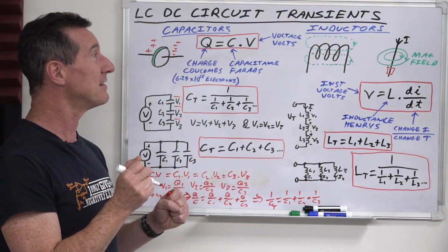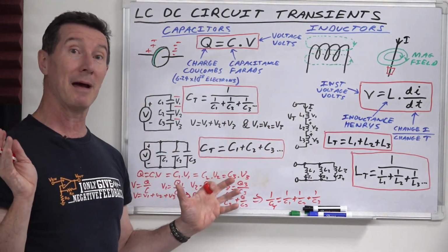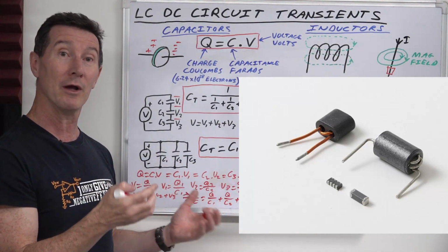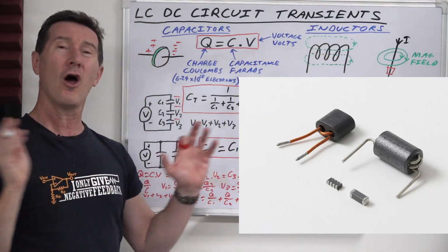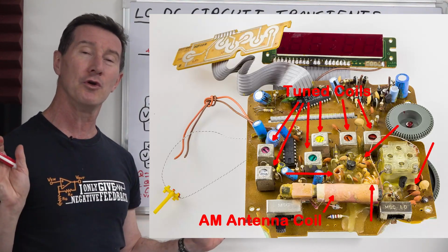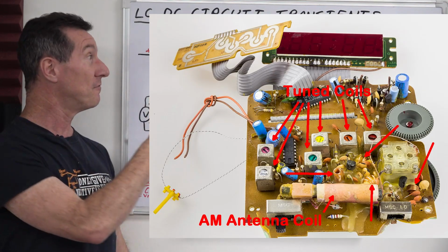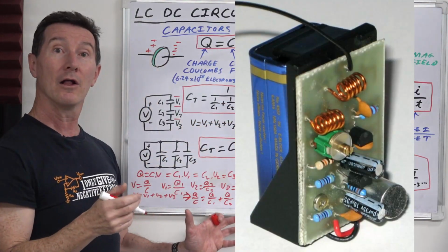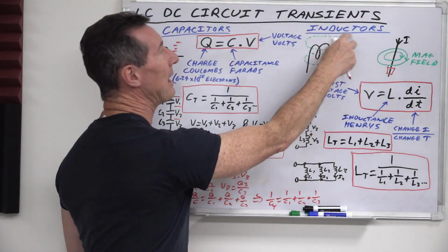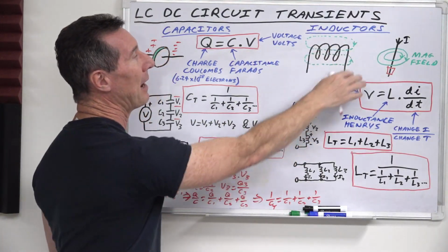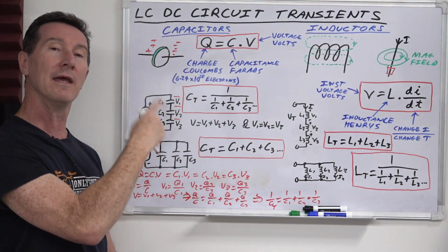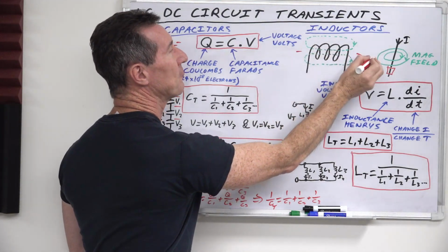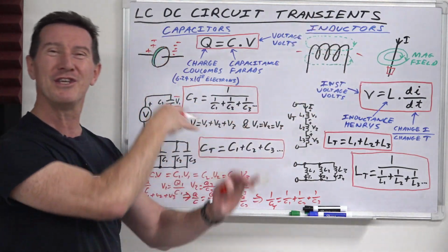bit more effective. But anyway, the way you usually make inductors more effective is to have multiple turns, i.e. make them into a coil, and they can be a physical air coil like that. Open any old school RF radio tuner and you'll find little coils of wire like that. When you coil them like that, the magnetic fields add up and pass through the multiple coils. So that's why you wind inductors into a coil. Then you can put ferrite cores through them, or you can make them into transformers, and you can do all sorts of stuff.